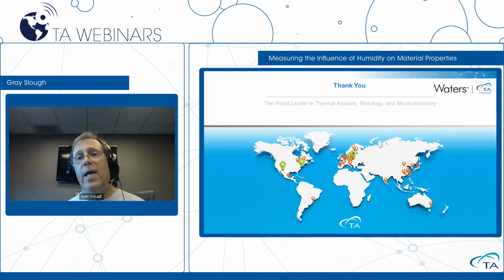You can also say that if the change in weight or the change in dimension drops below a certain value, then move on to the next step. For instance, in the Discovery assay, step the humidity in steps of 10%, hold for 2 hours unless the change of weight is less than, say, a tenth of a microgram over a 10-minute span.